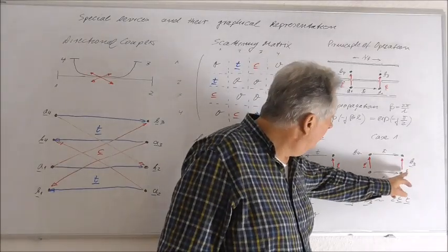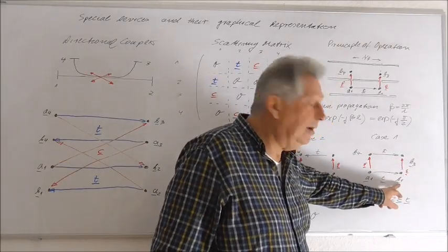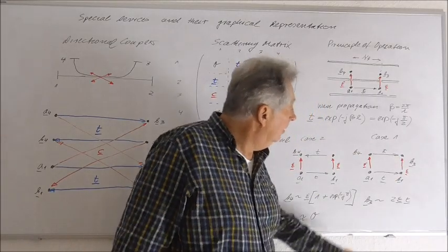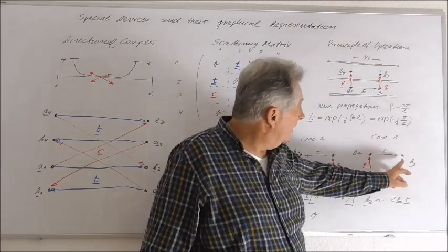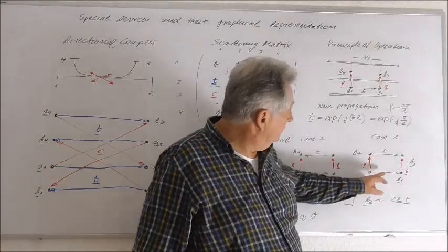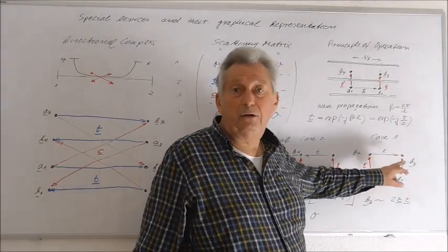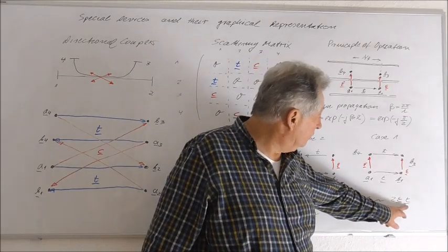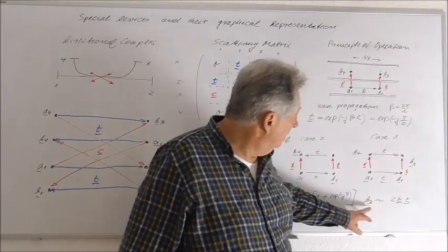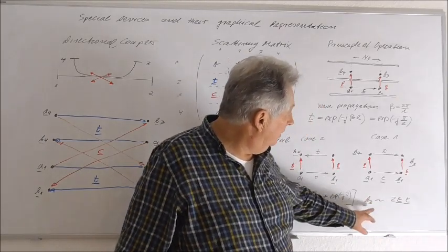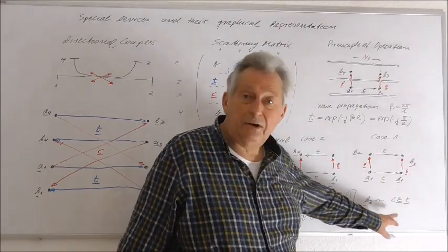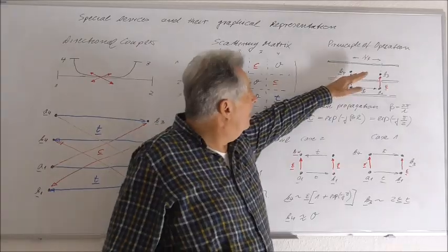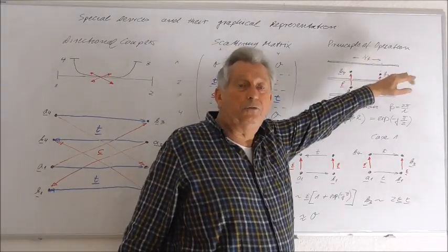And here we have again the wave amplitude B1, also a part of the wave amplitude will be coupled and they will add in B3, but since the two transmission factors point in the same direction, we will get the same phase shift here, and we will get that B3 is proportional to this expression. This means now that we have a certain coupling to port 3.